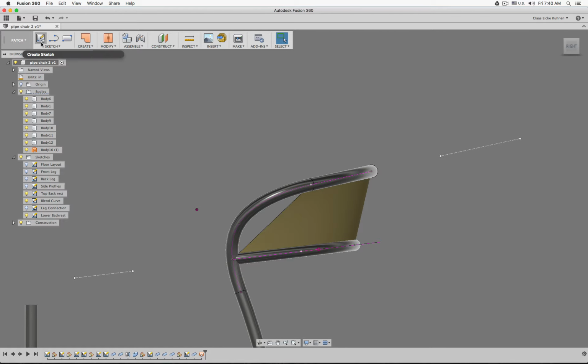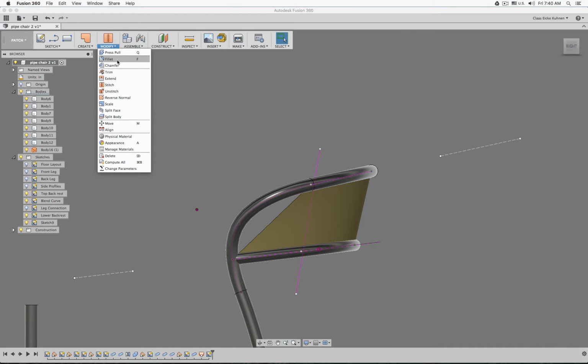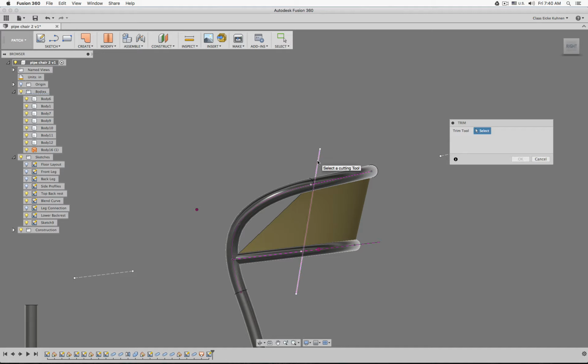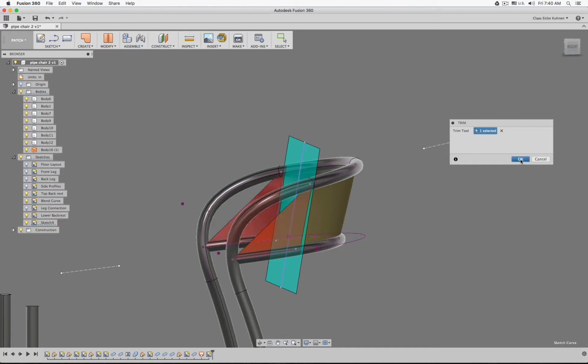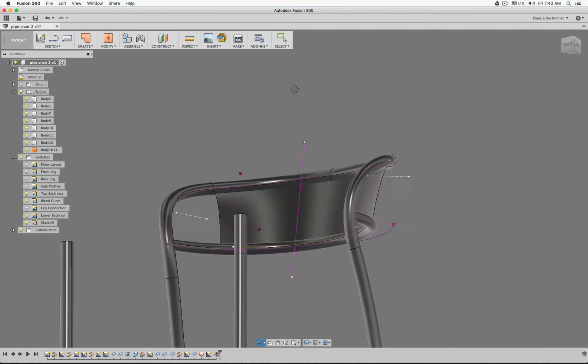And we could, for example, make a new sketch, or in any of the sketches we have, simply create maybe a line. Let's say like this. This line I will move to there. Stop sketch. Because with this line now I can turn on the trim command and then trim these parts cleanly off. So they're gone. Okay, there.